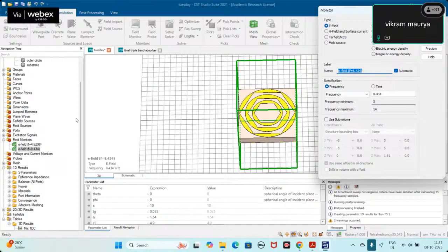After applying it, in this section, you can see your setup. Is it here or not? Then again, for the third, 12.559. Okay. Then again, press apply and then press OK, I will show you. If you apply, then the third resonant frequency will also be applied. Okay. All the three frequencies and their electric field have been applied.